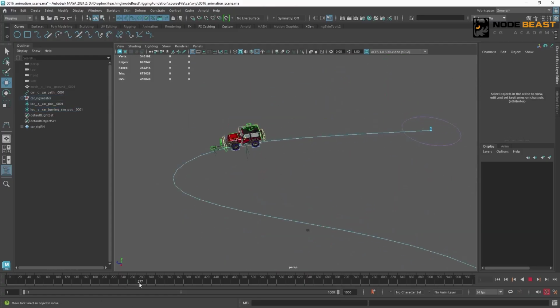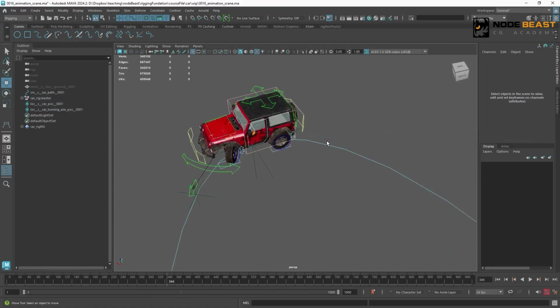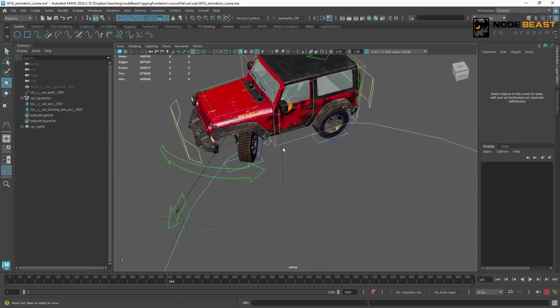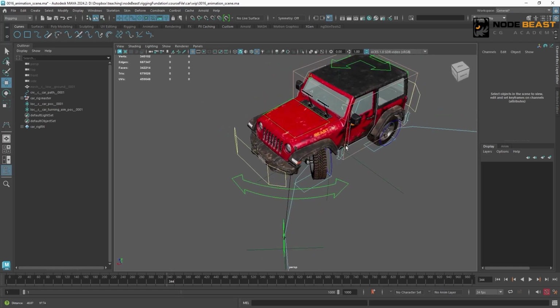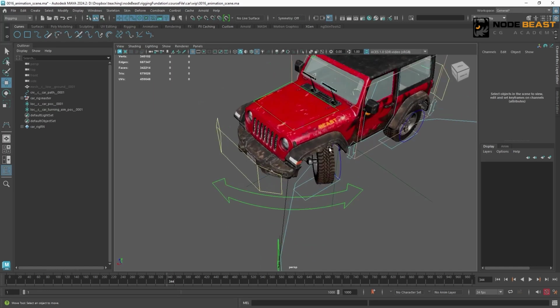There's one thing about the steering I'm still not satisfied with. Look, like here there is a very sharp turn. In this situation, you'll see the car's wheels here turn to a very extreme angle. This angle looks very unrealistic, because a real car shouldn't be able to turn to such a large angle. We mentioned when discussing steering rigging before, the general wheel steering angle is roughly between 30 and 40 degrees. Some might reach 45 degrees. But it certainly won't be a large value approaching 90 degrees.